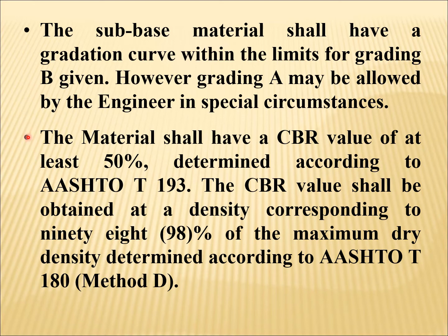The material shall have a CBR value of at least 50% determined according to H2T 193. The CBR value shall be obtained at a density corresponding to 98% of the maximum dry density determined according to H2T 180. So you know the CBR stands for California Bearing Ratio. It is a penetration test. So at least 50% value is required for subbase material.